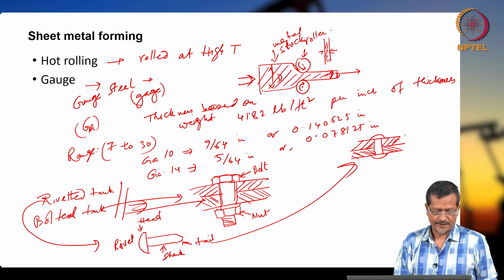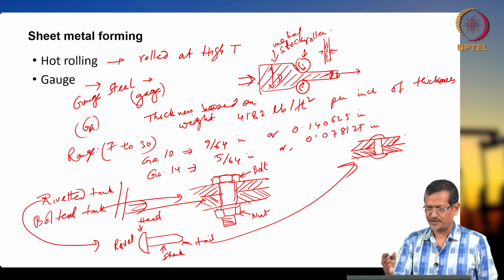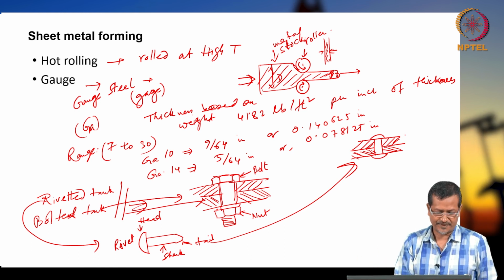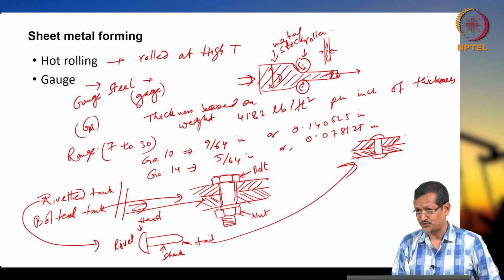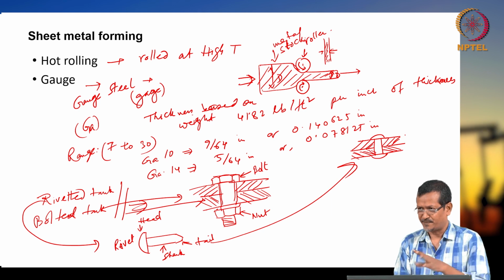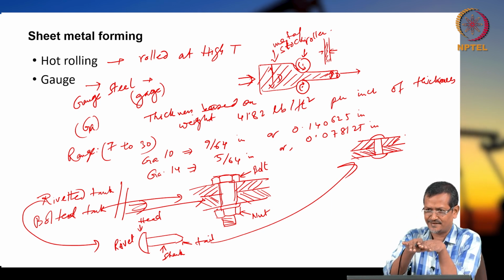They are cumbersome and time consuming to uninstall. If you are uninstalling or removing, it is very difficult for riveting. Limited clamp load, actually designed for permanent or semi-permanent joints, almost permanent actually. If you say purely permanent, complete welding will be permanent actually.